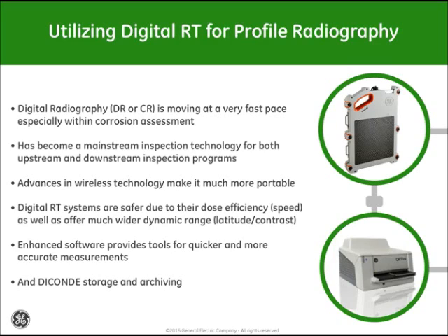So the digital detector systems are safer in most cases if you compare them to film, because they capture the image so much faster than film does, and they offer a much wider dynamic range, both in latitude and contrast, to provide better detectability of defects as you perform these inspections.